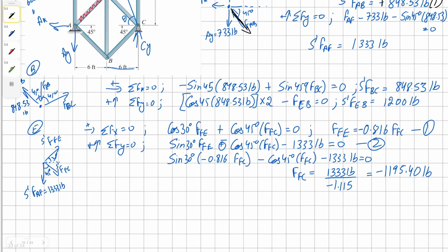For force FC, we can change it over to this positive solution, and this also tells us that this member is in tension. Even though this is not our final answer, we don't really have to tell if it is in tension or compression, but it's good practice.